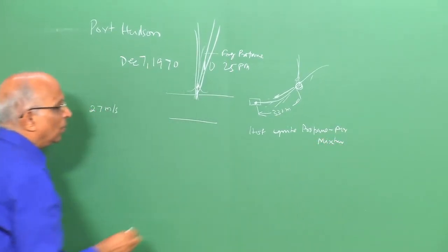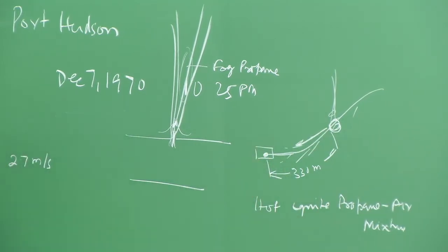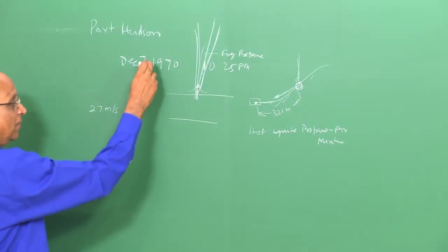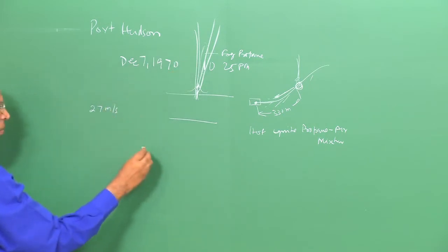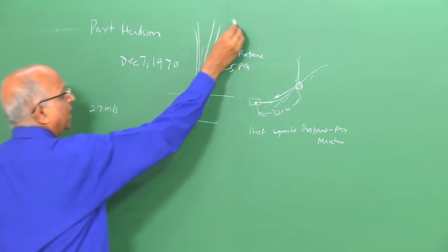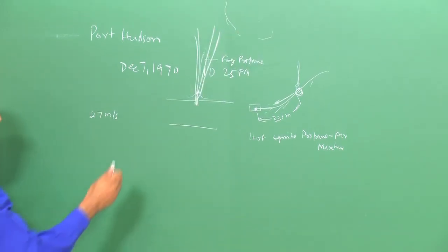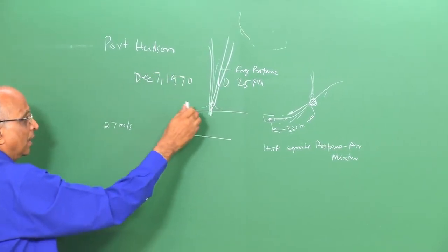Now we want to look at the dispersion of propane downhill along the wind, and 2 things we realize. One is that it's night time. We are also told that the sky is fairly clear, which means the cloud cover above this area is low. The temperatures are around minus 1 to 0 degrees centigrade, a cold night.